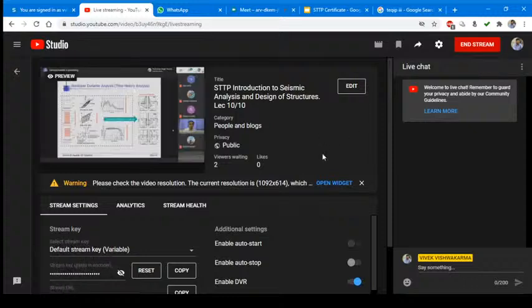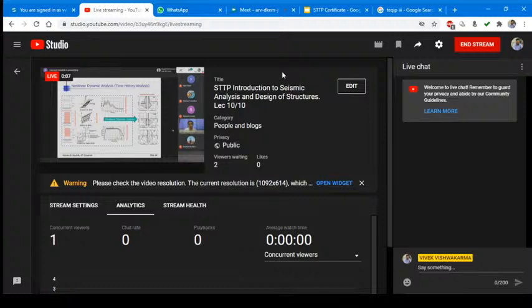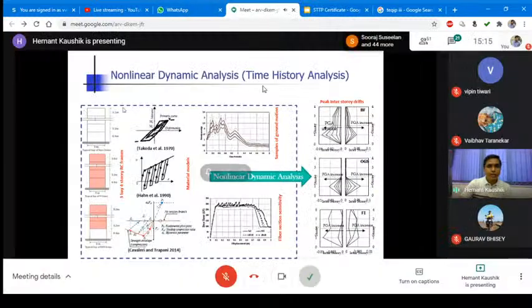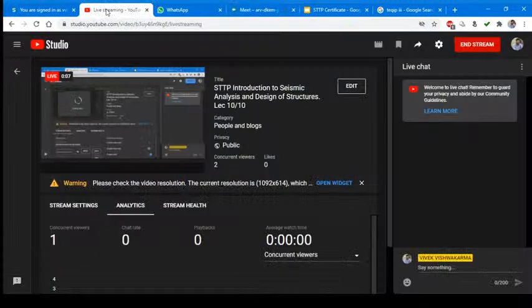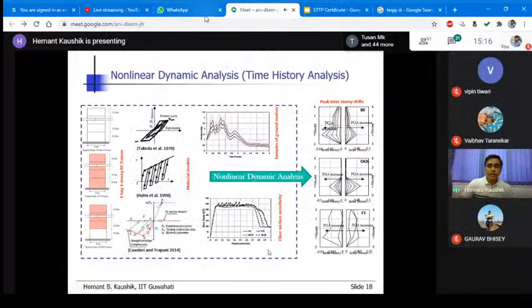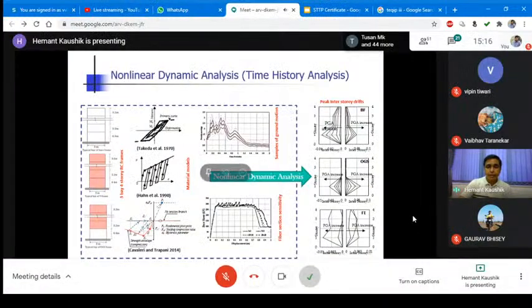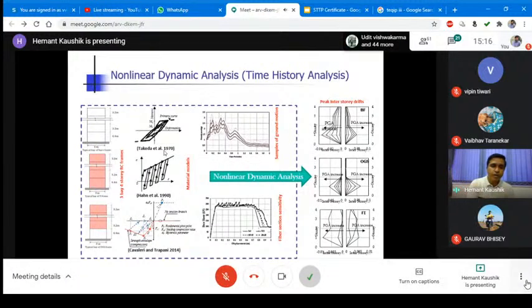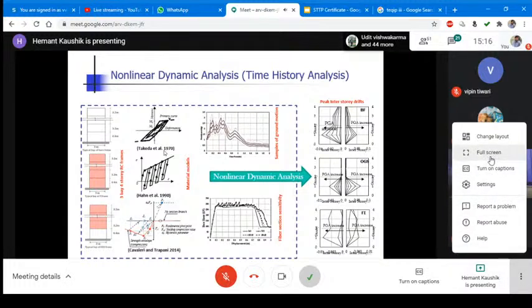the material properties. So this is up to this point, and not the full curves here, only the partial curves up to this point was used in the pushover analysis. Okay, but in dynamic analysis now you have to specify the ground motions also, right? You have to specify the section properties in a different manner. You have to specify the material properties in a different manner. So the type of input quantities required here is huge.